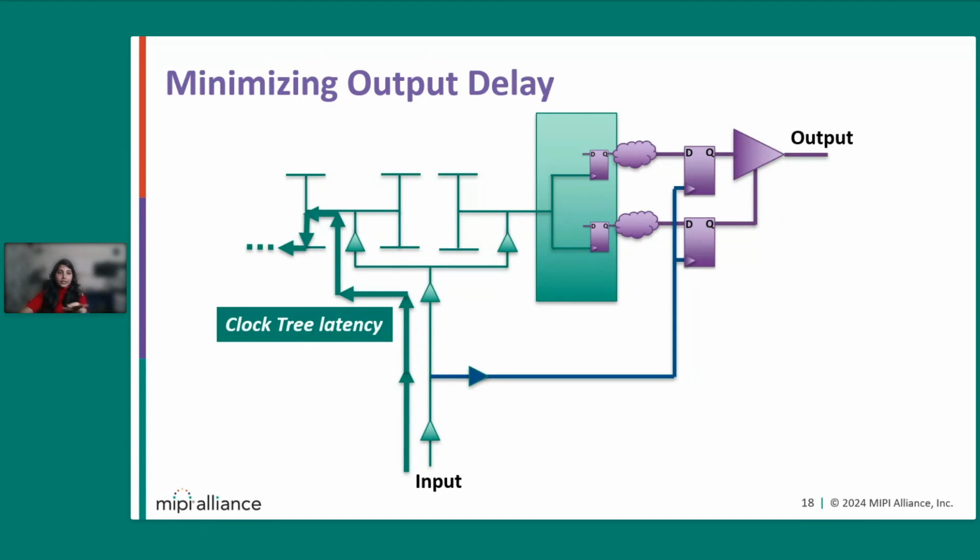So since we are creating a skew in which your output register clock will be fast enough compared to your main clock tree, the only thing is that here you are compromising with your setup time available. By keeping this you are making your hold violation very good, because at the cost of setup violation there will be very little skew between these two paths. So this will not be consequential, because here we have enough setup margin.